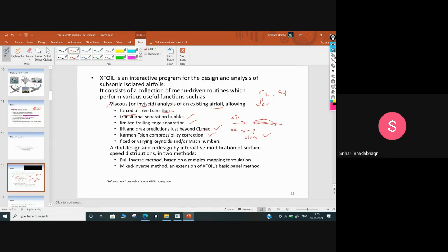And especially for this aerofoil, the minimum width that should be taken for this aerofoil section is 3 feet. Otherwise, that geometry is not sufficient to find the quotient of the lift and the drag.